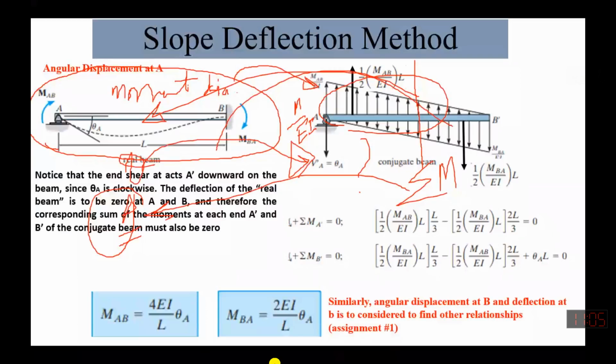So as we know here, slope is 0, we know shear at this slope is 0, theta is 0, delta is 0. So that means there is no movement, no shear. So the same we take for the end condition as well. There will be no end condition which is resisting any movement or shear. So that's why we keep it as a free end, because it is not resisting any rotation or shear or any movement over here. So this is the concept behind using this methodology actually.